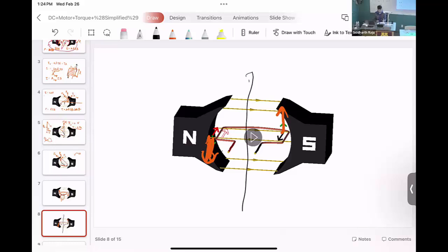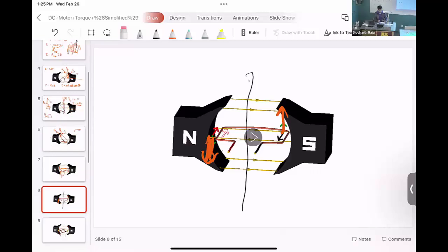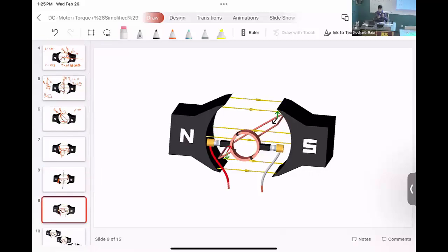We can do this when we sense somehow where the conductor is. If the conductor is on the left, pass current in one direction. If the conductor changes, reverse the voltage and you can pass current the other way. But people had created ingenious apparatus to make the system run even before power electronics existed. Even if you have power electronics, there is another problem that's not solved, which is that the wire will get twisted eventually as it keeps rotating. So this thing called a commutator, this is a commutator. This addresses two problems.